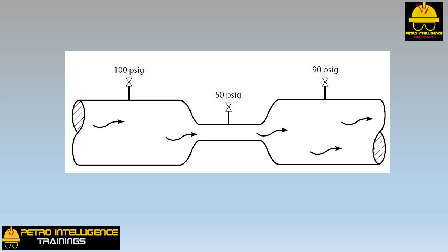The reason the pressure at the end of the pipe in the picture is lower than at the inlet to the pipe is due to frictional losses. The orifice coefficient K takes into account both frictional pressure losses and conversion of pressure to velocity. The frictional losses represent an irreversible process. The conversion of pressure to velocity represents a reversible process.